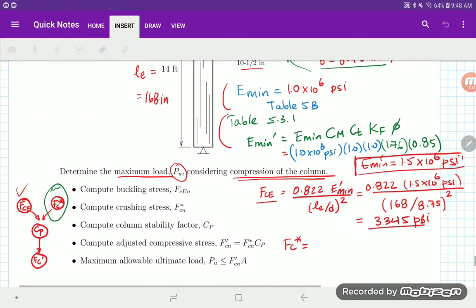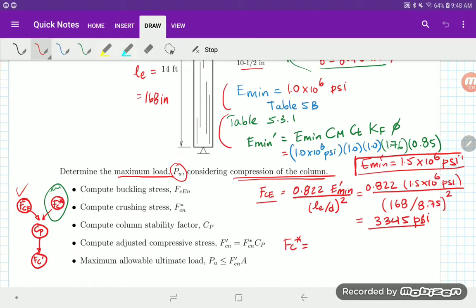So moving back and plugging in our equation, I'm going to have our reference value F sub C, then moisture, temperature, and then our adjustment factor to go from ASD to LRFD, phi, and lambda.